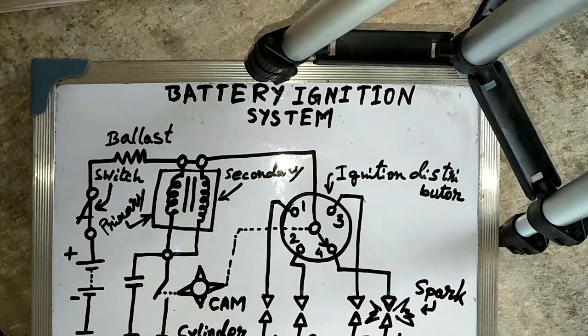So let's start. As air is a poor conductor of electricity, an air gap in an electrical circuit acts as a high resistance. But when high voltage is supplied across the electrodes of a spark plug, it produces a spark across the gap. When such a spark is produced to ignite a homogeneous air-fuel mixture in the combustion chamber of an engine, it is called a spark ignition engine.